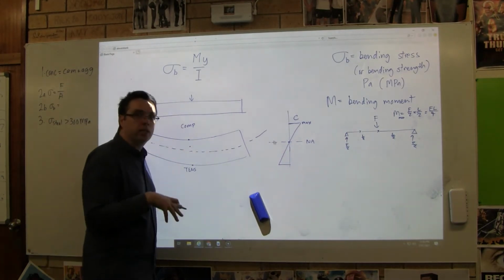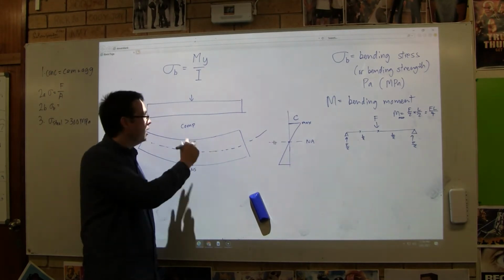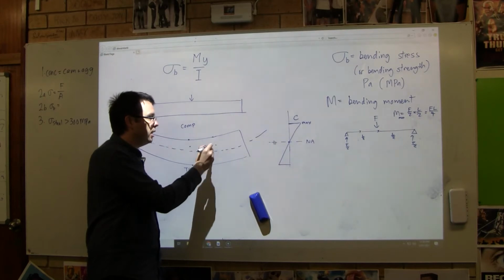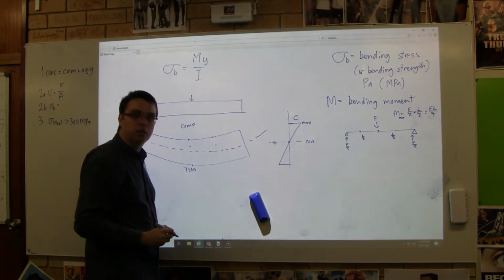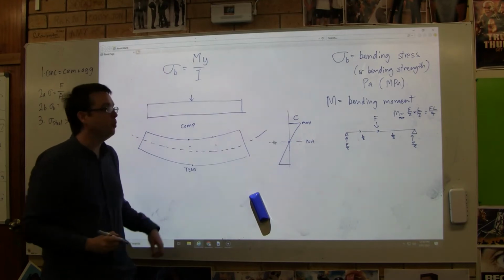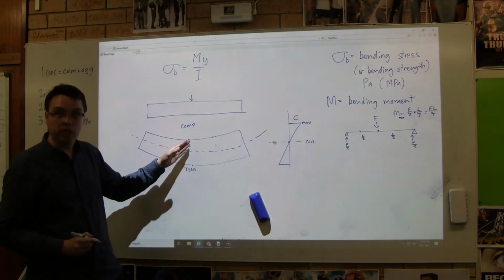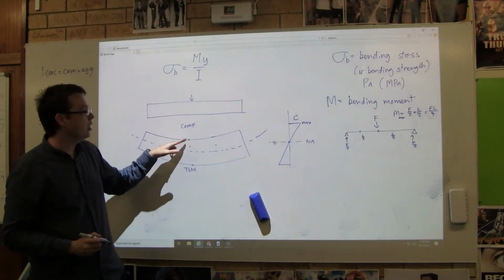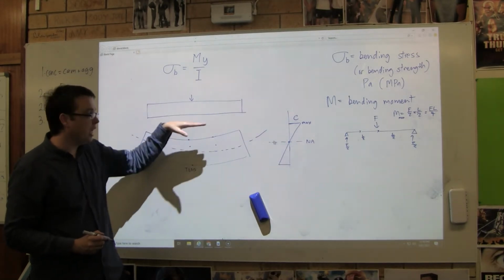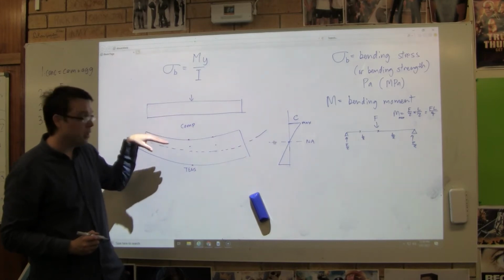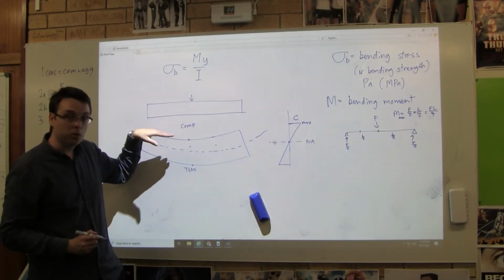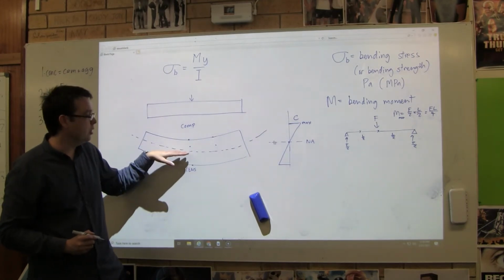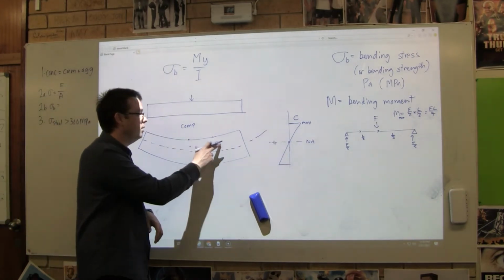So what we find is that it's interesting that in this beam, this is the maximum bending, this has less bending, and this has less bending again. Yeah, because we know bending is at the maximum in here, and we know that the stress is a lot bigger on the outside layer. The layer next to the paint is under a lot more load, under a lot more stress than the middle. The middle is doing nothing; it's just sitting there.